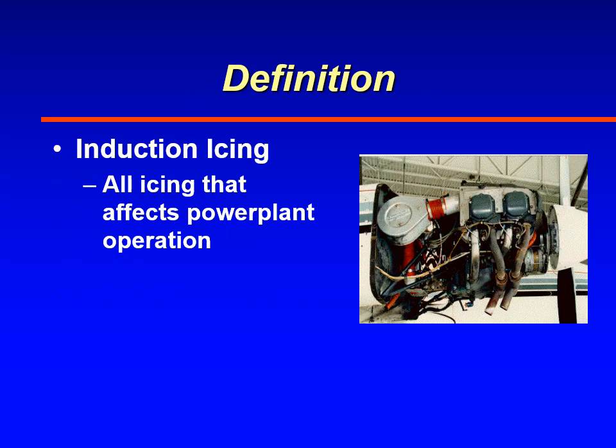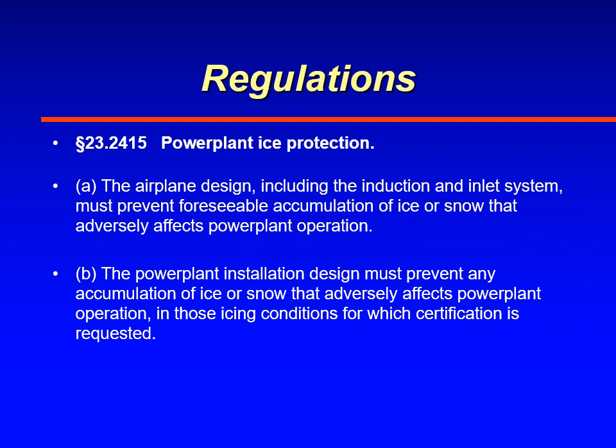So induction icing is any icing that occurs with the power plant of the aircraft, whether it be a piston engine or a turbine engine. Part 23, which deals with the certification of light aircraft, has a regulation, 23.2415, that deals with power plant ice protection.